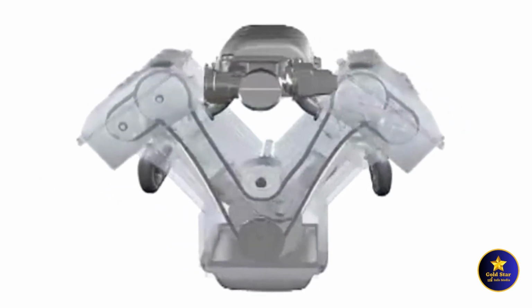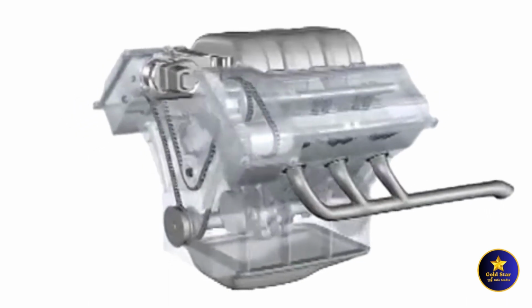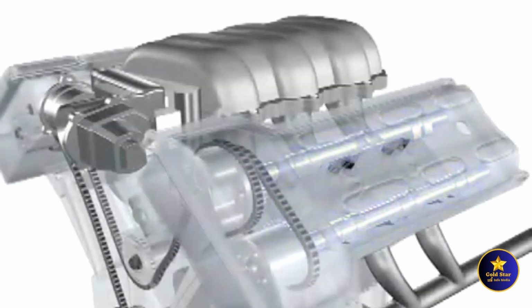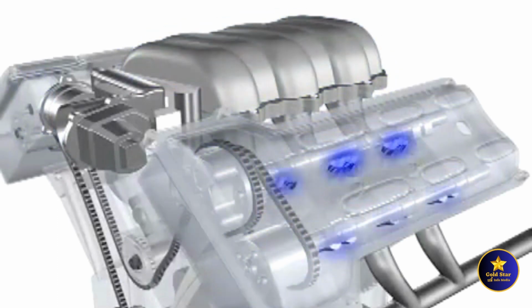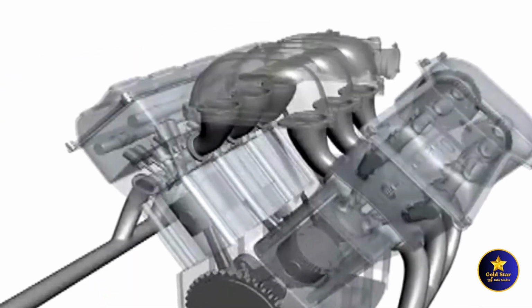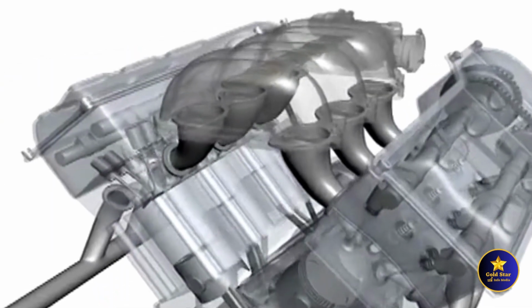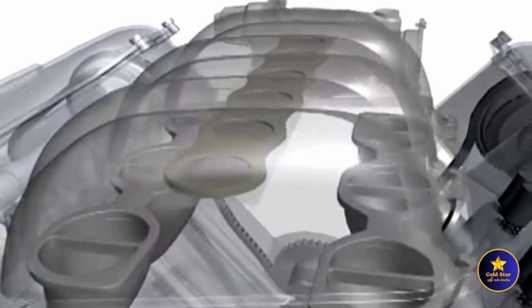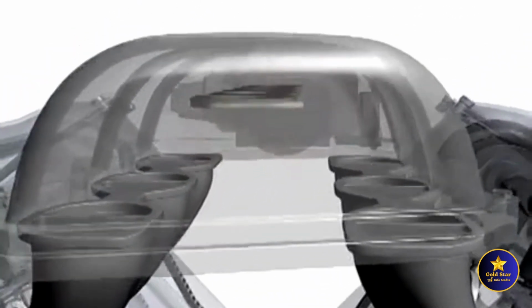The more efficiently an engine breathes, the more efficiently it will produce power. Toyota engines incorporate a number of features and components that are designed to help the engine breathe more efficiently. An acoustic control induction system, or ACIS, automatically varies the length of the runners in the intake manifold to maximize the airflow into the engine and to provide more usable power throughout the entire RPM range.